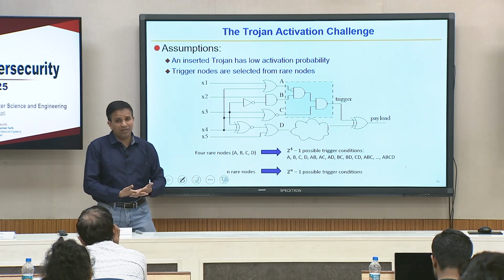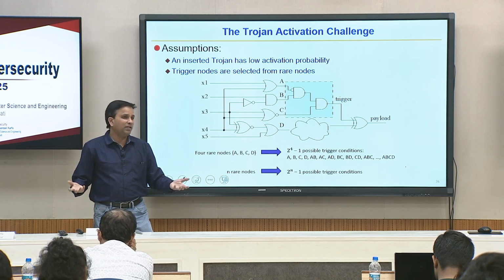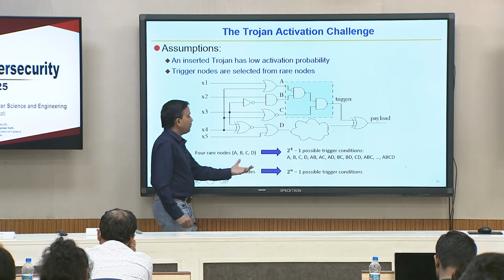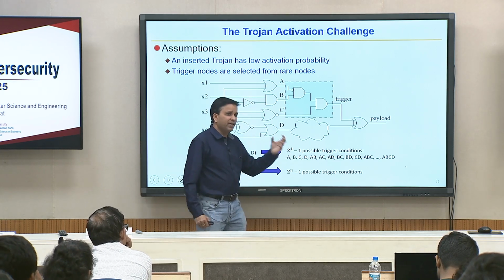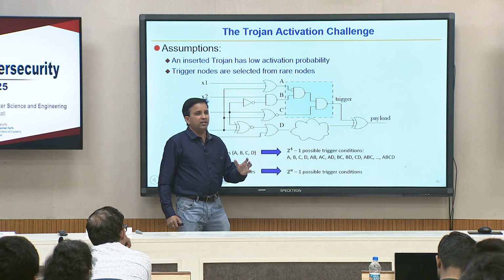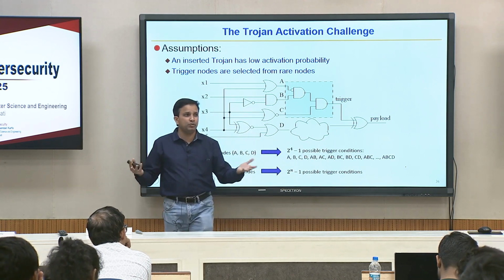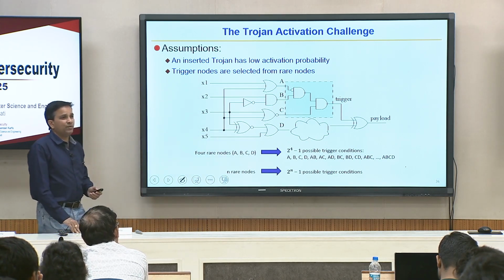You can artificially reduce the threshold to 0.00001, but you do not know what the attacker is trying to do or which signals they are trying to take. But the point I wanted to mention is that even if you know it is a rareness based trigger, the number of possible triggers is exponential, huge. So, you will not be able to generate one test for each of them.